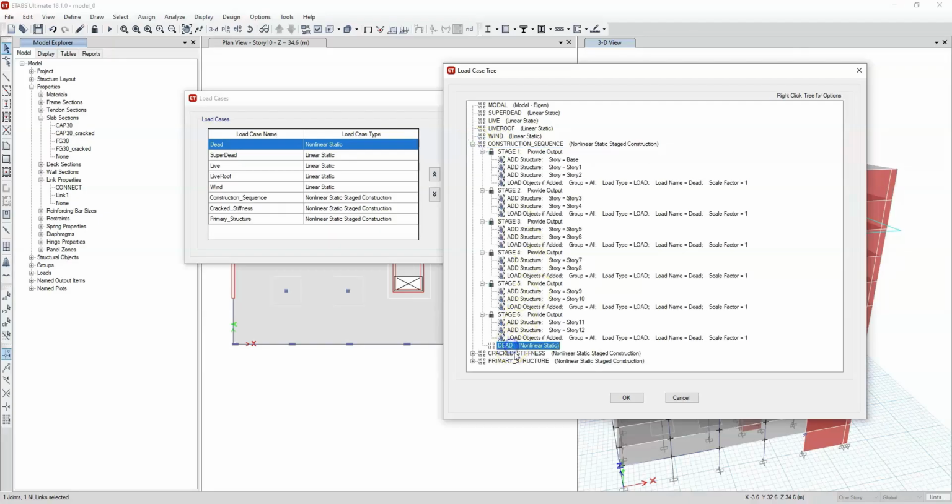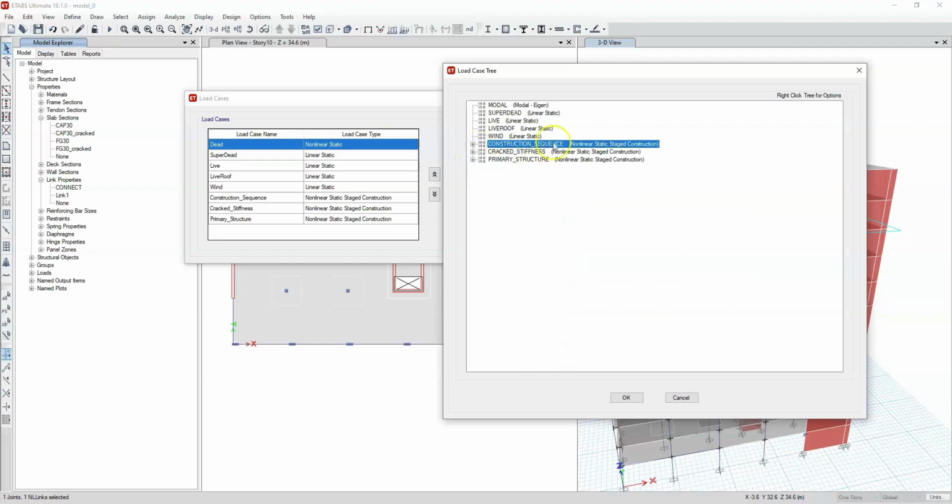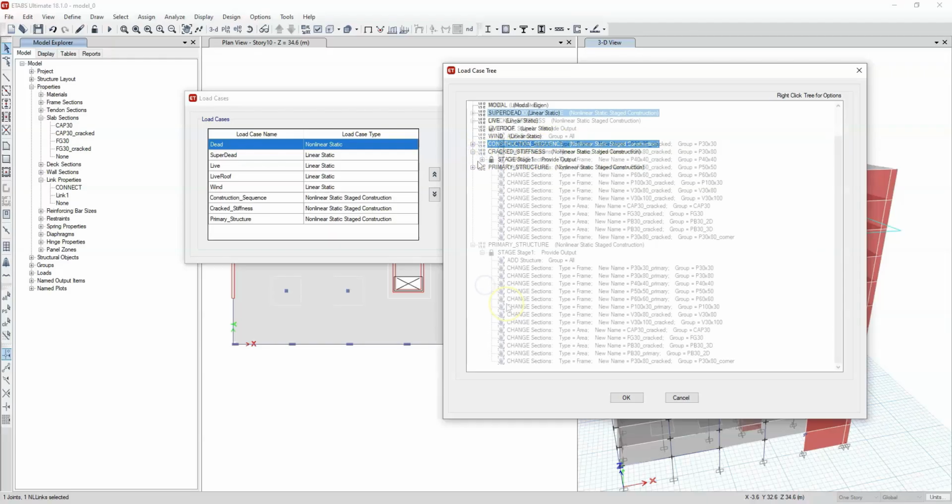What we do is simply ensure that at the end of the structure, we have a dead load case that basically starts from the previous nonlinear staged construction load case. The final internal forces we have from this load case are simply the gravity loads, the final permanent loads after the construction process. This is just one model that is not related to the seismic part. The other 2 are related to the seismic analysis.